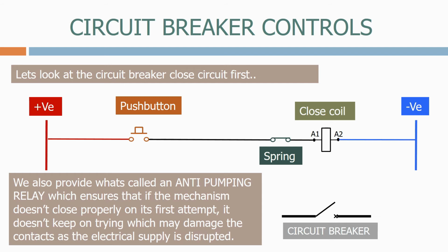We also provide what's called an anti-pumping relay, which ensures that if the mechanism doesn't close properly on its first attempt, it doesn't keep on trying, which may damage the main contacts as the electrical supply is disrupted.